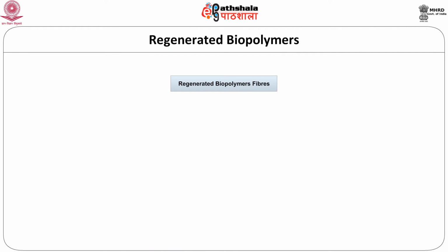The artificial fibers are categorized into different groups based on their extraction as regenerated biopolymers, synthetic polymers and minerals. Regenerated biopolymers are the fibers obtained by modifying the cellulose obtained from plants. The manufacturing process consists of bringing a natural high polymer substance into solution in a suitable way and extruding this solution through a nozzle, regenerating the same high polymer in the form of a solid filament.